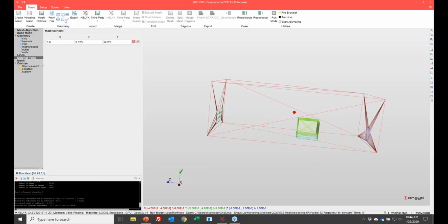So in addition to the geometry that I could have imported, I can also use these primitive shapes to do things like create volumetric refinement boxes. If you're clever and you want to create a domain entirely with these primitive objects, in theory you could. And I've done a lot of this. Say you're given a fan blade and you want to create a wedge geometry on one of the single fan blades for this entire experimental domain, you can use all of these different primitive objects very easily.